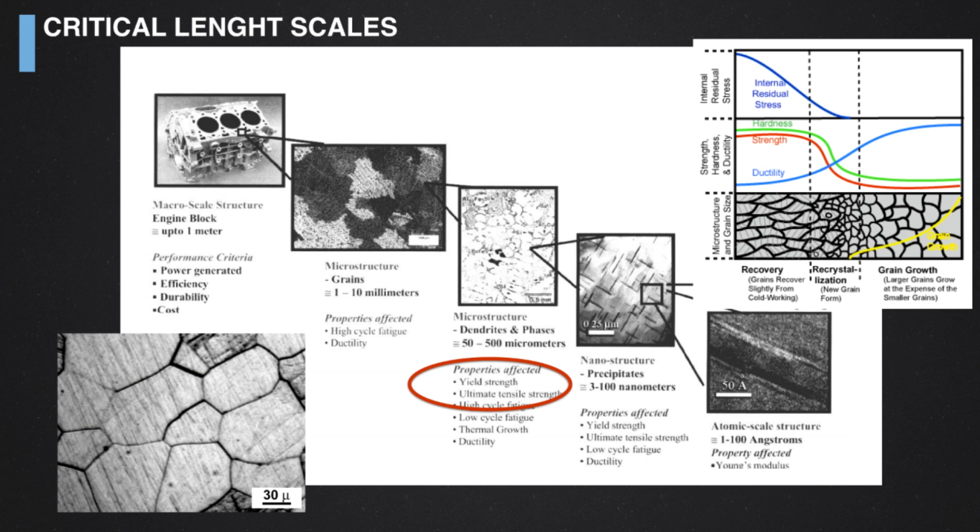particular its ductility. Because when you apply a mechanical stress to the material, all the grains which are small enough and have a huge amount of grain boundaries between them are easily flowing at the same speed of your application of the mechanical stress. And this is important if you want to prepare a structure that is also plastically deformable, not only elastic. Okay? So depending on your needs, you should carefully select the crystalline structure.